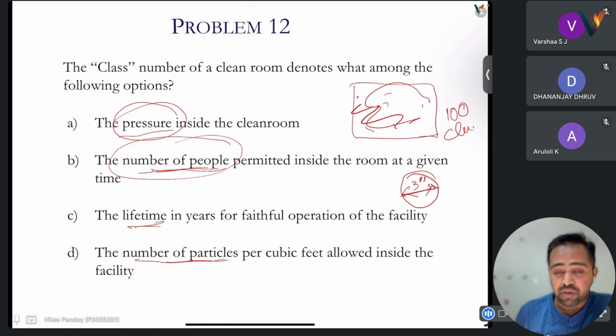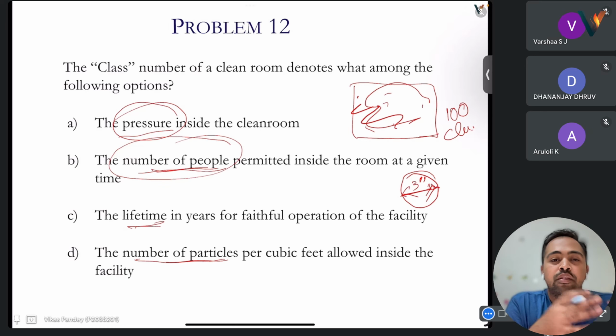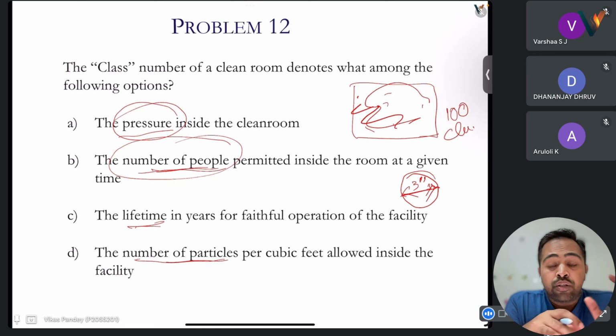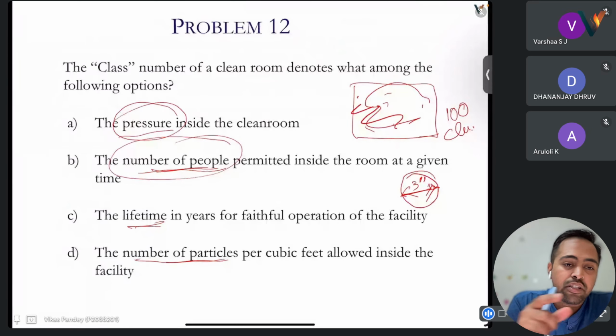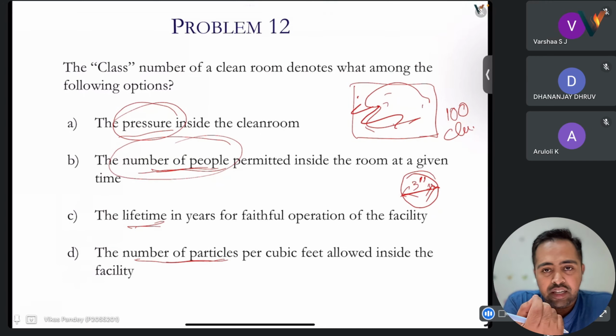So a lot of precaution is needed. If we are calculating that 100 particles are actually allowed, those are the maximum allowed ones. So it is very important to have all these processes inside a clean room, because it will increase the probability of having good devices. If we say 700-800 small particles of 0.5 micron or less are fine, not an issue.